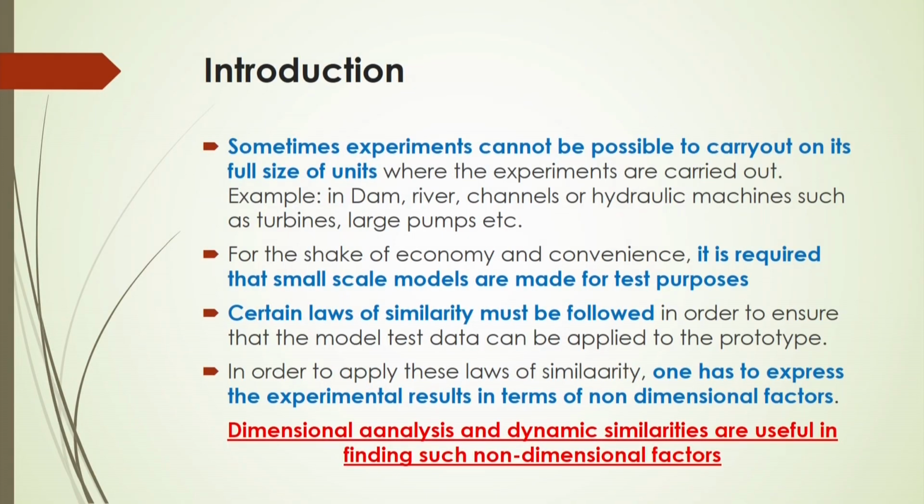In order to apply those laws of similarity, you have to express or interpret the experimental results in terms of non-dimensional factors. If the dimensions of the physical properties or geometries of the systems are different, then you will not be able to scale up to large proportions.